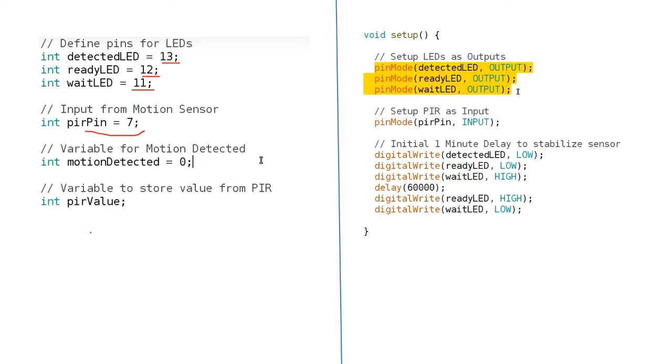So once we have declared how we have connected, remember this, when we talk about defining, making definitions, sometimes we talk about variables. But what we're trying to say in this particular section is that we are declaring, we are already showing Arduino what we are saying. First, we are saying we are going to use pin 13. We're also going to use pin 12. We're also going to use pin 11 to connect something like this. So it's like we're keeping some value here.